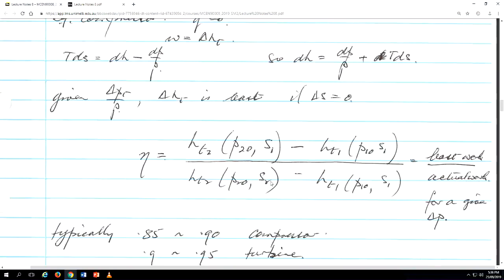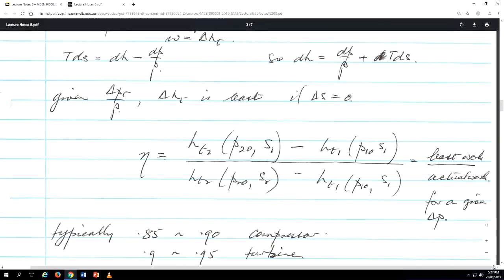Well, because a turbine will drop the pressure because you're going to take work out of it. The pressure will be falling, and all those boundary layers, you won't get separation in the same way. Whereas in the compressor, the boundary layers are likely to face rising pressure, and they're likely to separate. And you lose more efficiency if the boundary layers get thick and separate than if they don't. So that's why that's true.